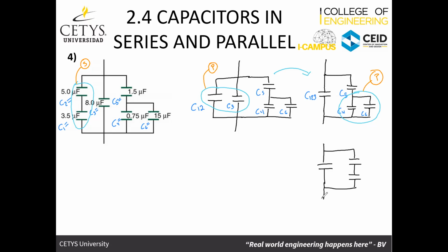And it's not in parallel because to be in parallel, remember the holding hands: both of the terminals have to be connected to both of the terminals of the other. So in other words, series are very picky when it comes to junctions and parallel are not. In series, if there's any junction in between the elements, it's not in series. It has to be a closed path.